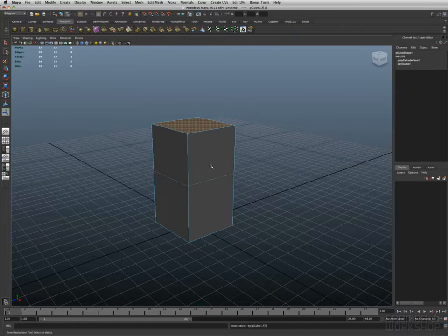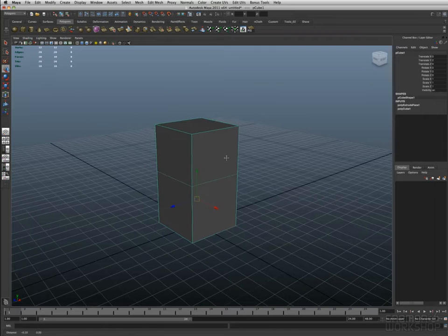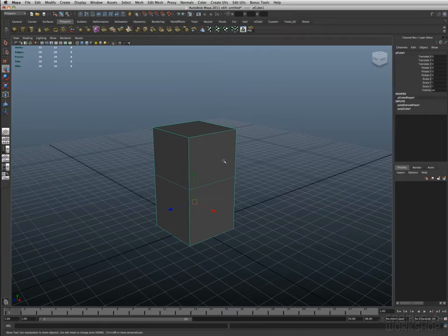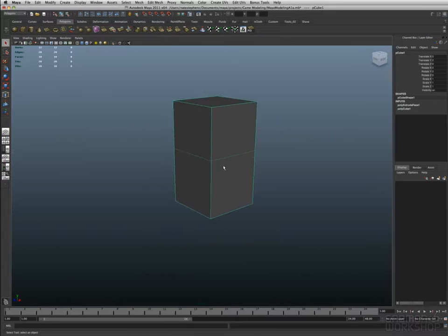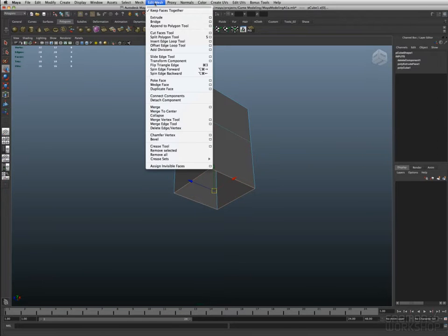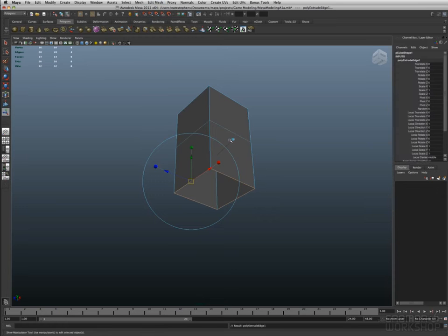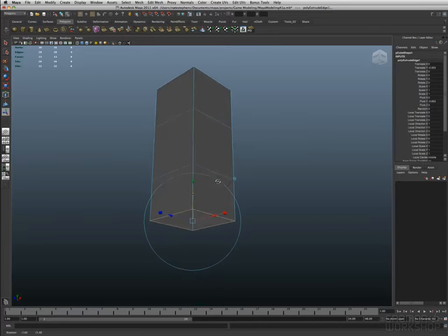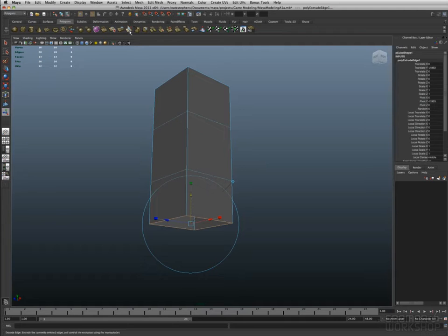And let's undo this. Now, extruding is not just for faces, and I'll illustrate that by hiding the grid here and deleting this face on the bottom. We can also do extrusions on edges. So let's select these 4 edges, go up to the Edit Mesh tab, click the Extrude button, change this to world space, and voila! You see we can now move along edges as well, which I find I use almost as much as extruding on faces.